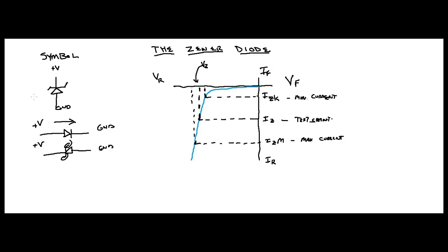Now, look at this line, this blue line, this current. This IZK, this point right here, basically is where this line starts to become linear. So in other words, it's come across the knee. This is known as the knee right here. This area can be thought of as the knee, just like you're sitting at a table and bending your leg.